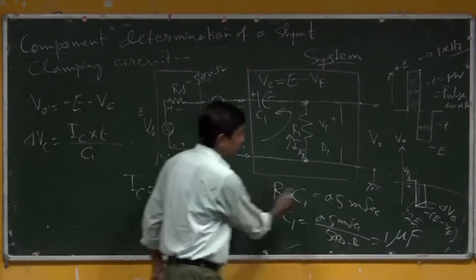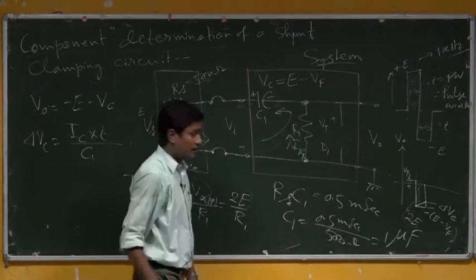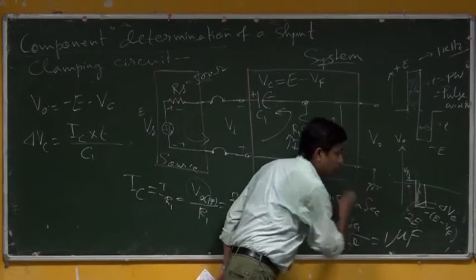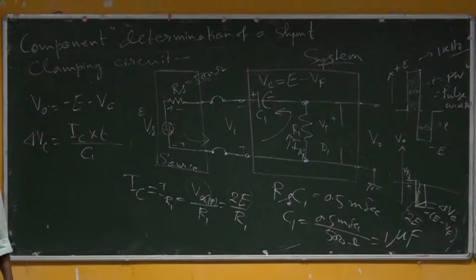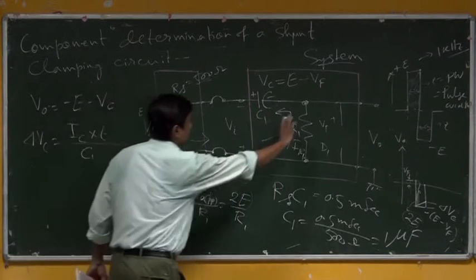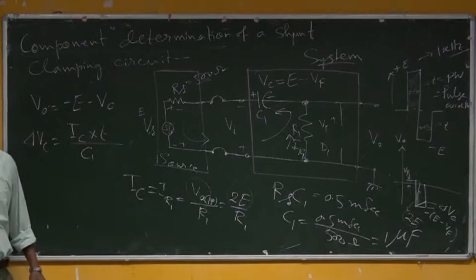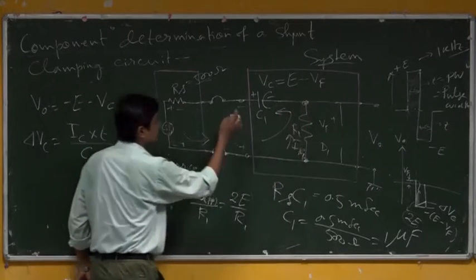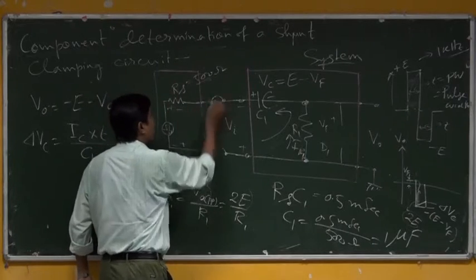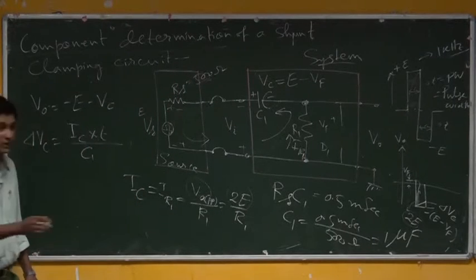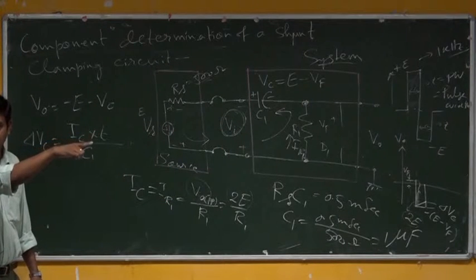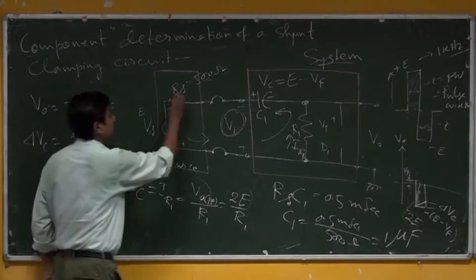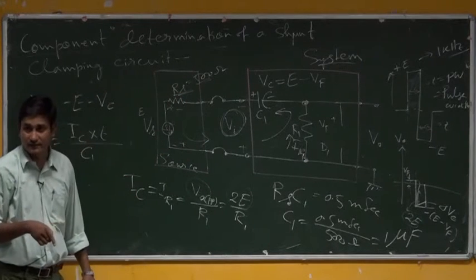Okay. Now tell me what should be the peak value, V0 peak to peak, today? Earlier the peak to peak voltage was 2E. Now is that peak to peak voltage 2E? Actually this voltage is the one which has come here, that is after minus Ic into Rs, that potential which came here as Vi has gone to that place. Is it not? This is the effect of this Rs which I am targeting in today's class.